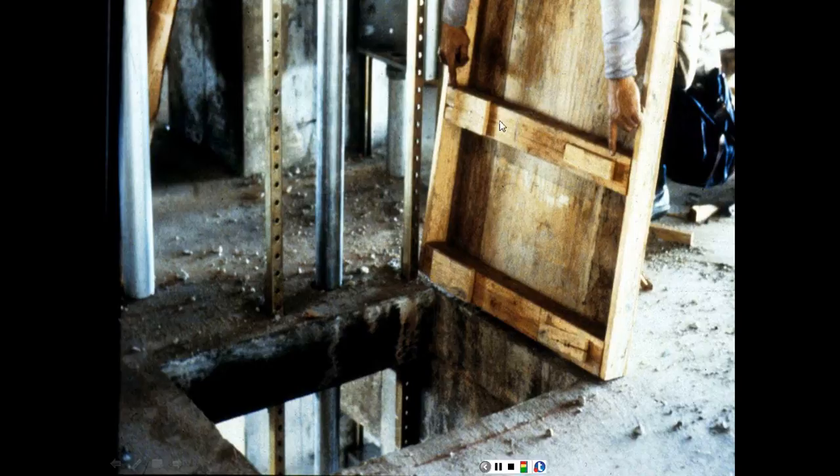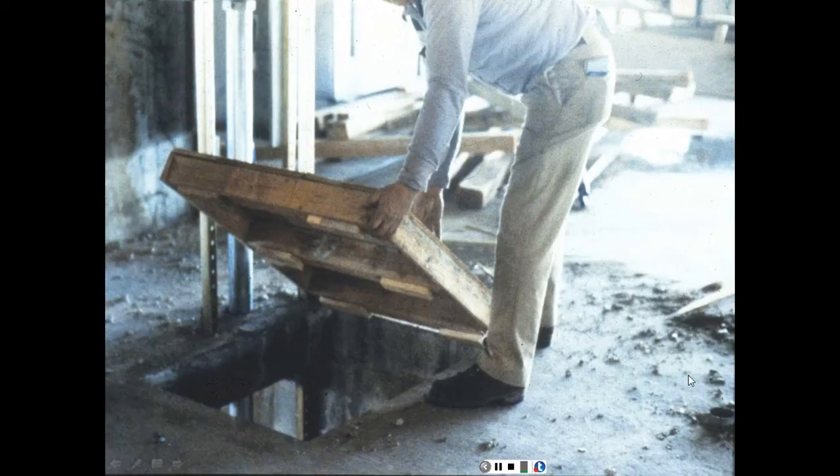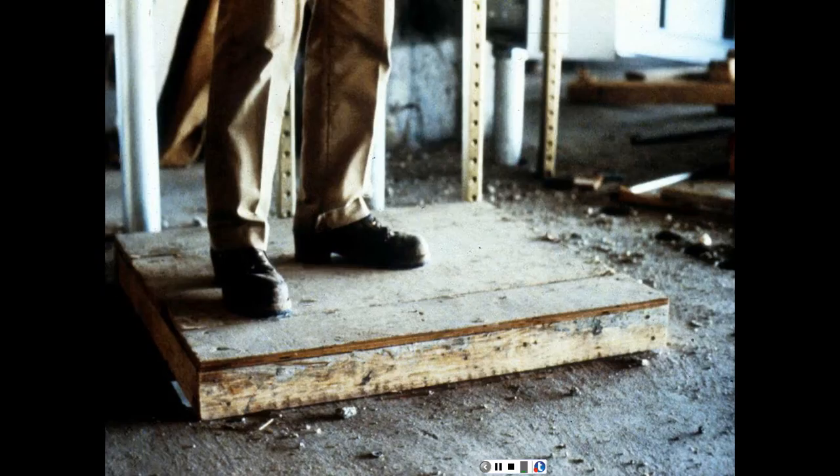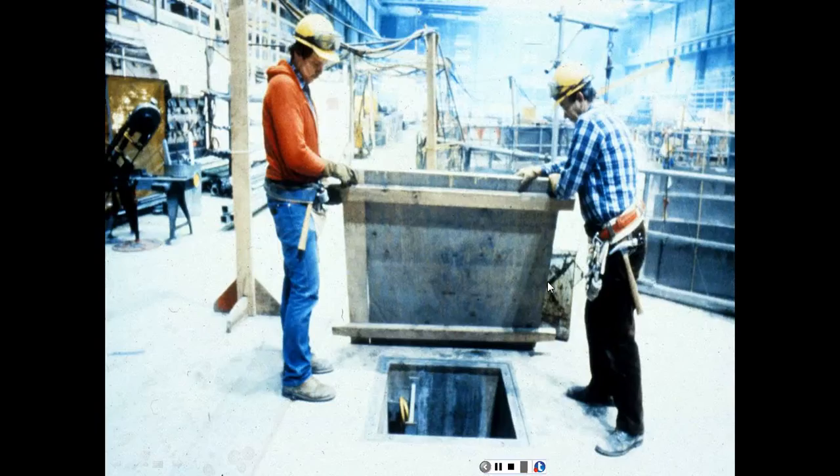So here you have to show how you can position that cover so that it doesn't shift, doesn't move from its place. And now it's properly installed, and it's strong enough for a person to stand on top of it. This is proper protection. Again, it shows here the steps of the installation, and we can see that the cover is much wider than the hole to make sure that we cover the whole open area.